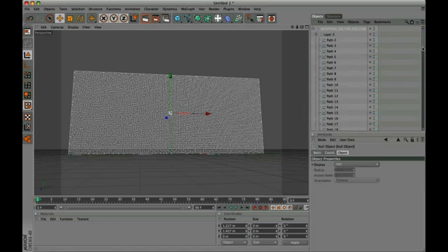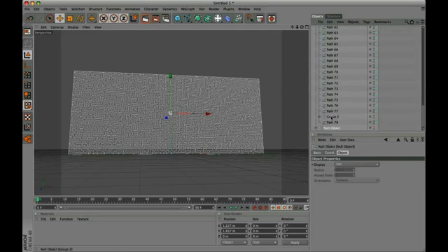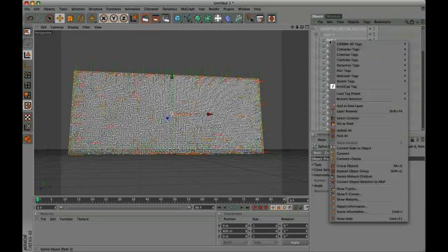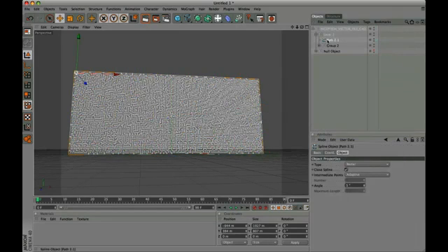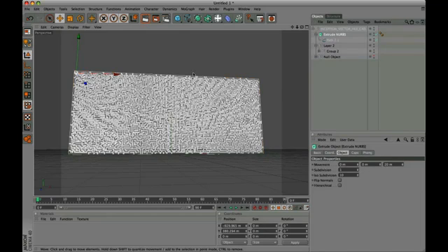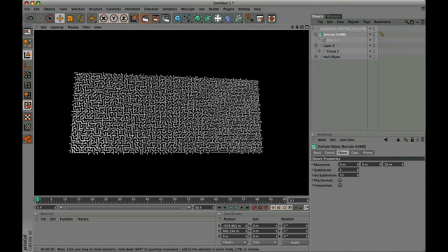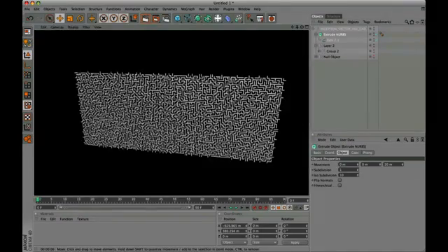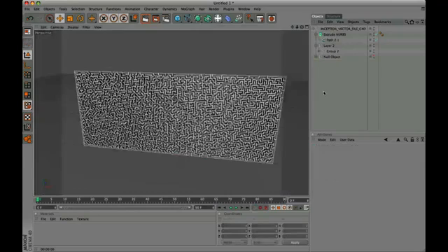Open the null object, layer 2, and we drag out the group 2 layer. We select the spline and join with the command Connect plus Delete. Drag out of the 2 layer and apply the Extrude tool. We do a render to see the result. OK. Rename Extrude Maze.